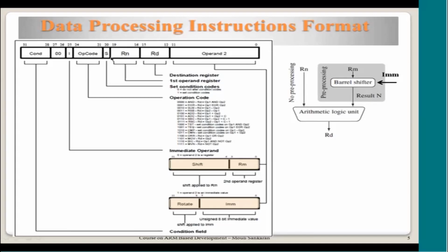Then processor, when it looks at it, will know that this instruction is not supposed to impact the CPSR flags, so let me not change anything in the CPSR and do only the operation requested by this instruction. So this is the way the processor interprets the instruction, and this is the way the assembler encodes your assembly instructions into a binary format, and it fits into the 32-bit format so that the processor understands that and accordingly acts on it.